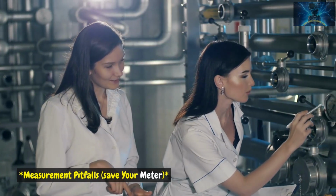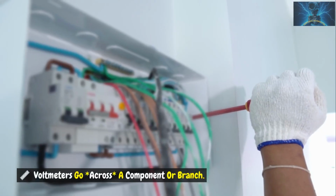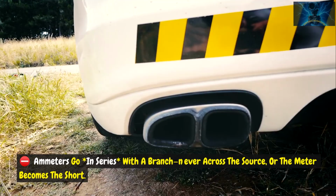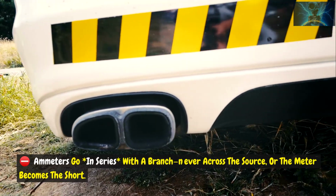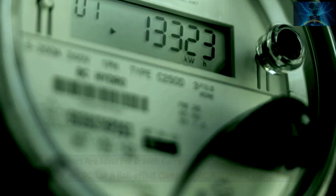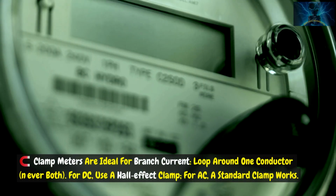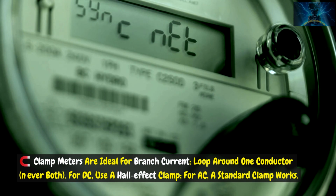Measurement pitfalls: save your meter. Voltmeters go across a component or branch. Ammeters go in series with a branch, never across the source, or the meter becomes the short. Clamp meters are ideal for branch current. Loop around one conductor, never both. For DC, use a Hall effect clamp. For AC, a standard clamp works.